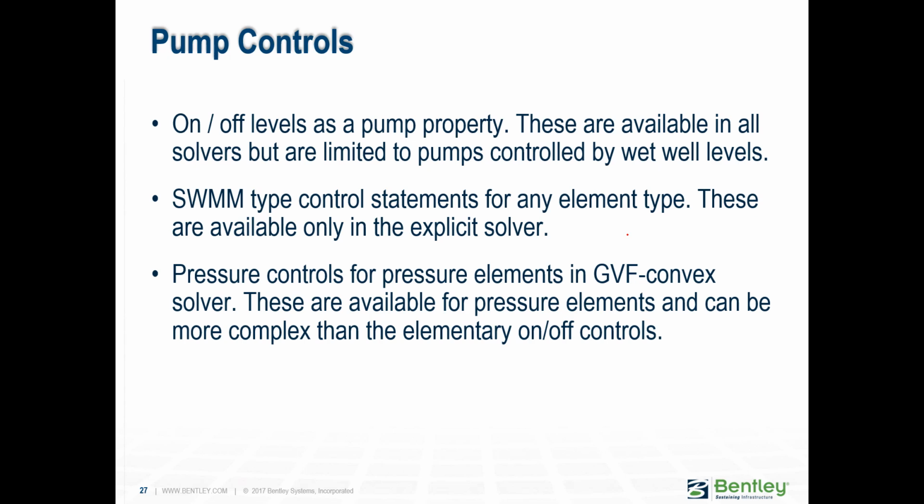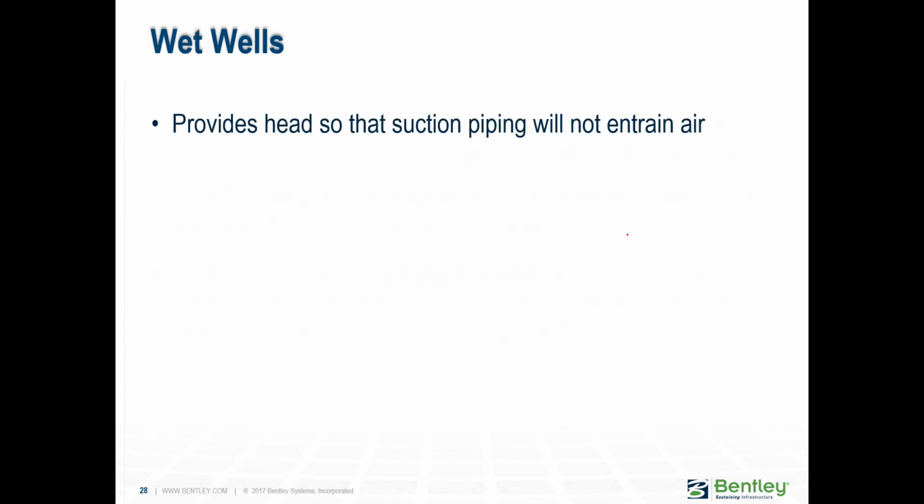But traditionally, a pump is controlled by the wet well level. So when it's really full, turn the pump on, and as it empties the wet well, turn the pump off, and then wait for it to fill and go on. Okay, so wet wells, again, most of the time control the pumps, but if you needed to do it differently, you could as well.